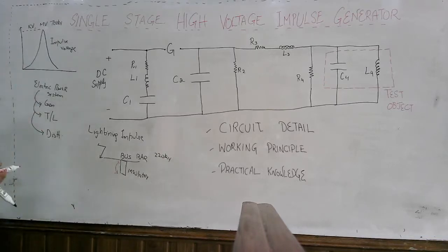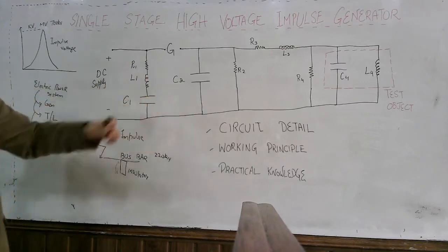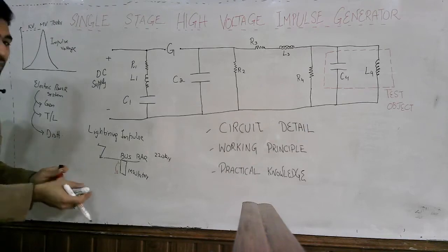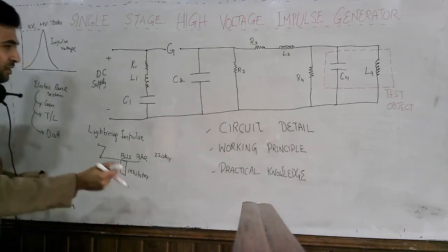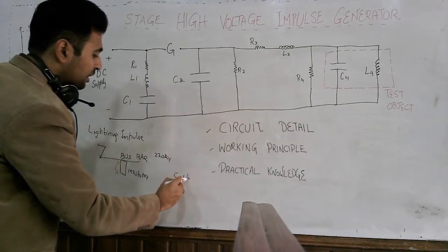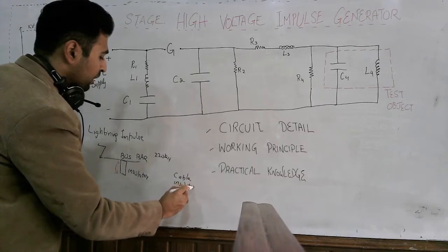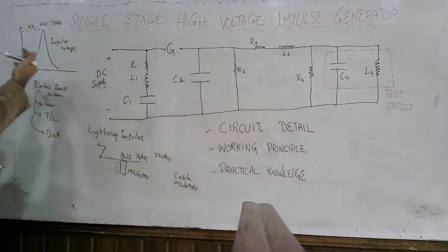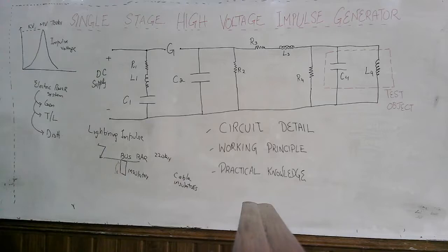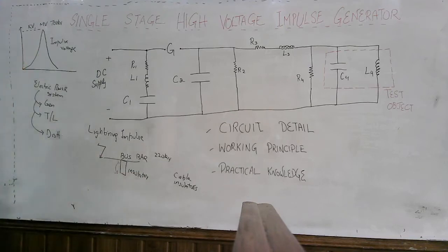So why are we interested in studying this circuit? Because we want to test these insulators, the cable insulators, so that against these impulses which occur in the system, we can see whether these insulators can sustain such impulse voltages which appear in our actual power system or not.